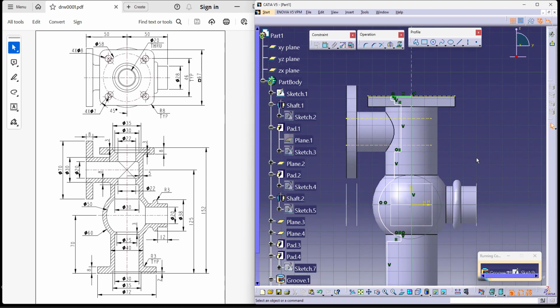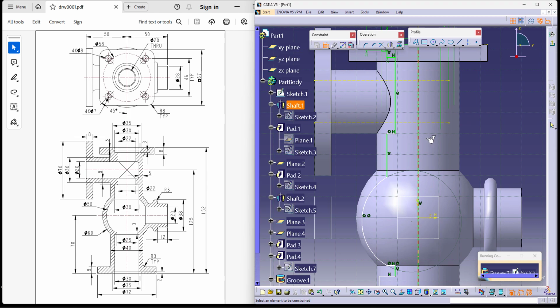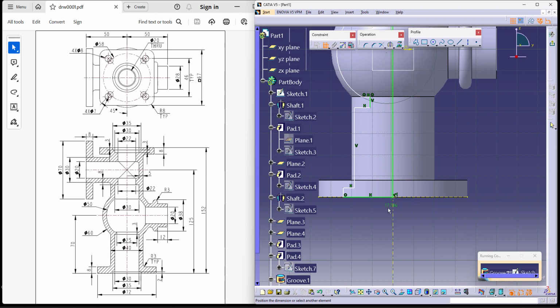Yes. Now, to begin, let us start dimensioning from the top. I have this as 3 first and the diameter as 35. I have this as 3 as well, but the diameter is 30 here. Now I have this one as well. The diameter is actually 22. Now I know the distance from this edge to this is 8, which is already given in the drawing, as you can see here. And I know that this particular dimension is again 30. So let me take that as 30 as well.